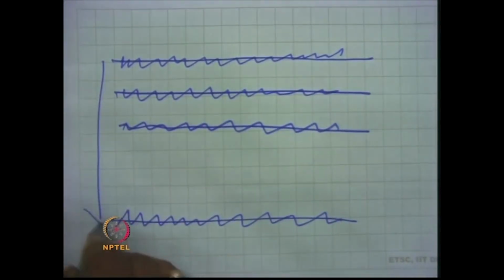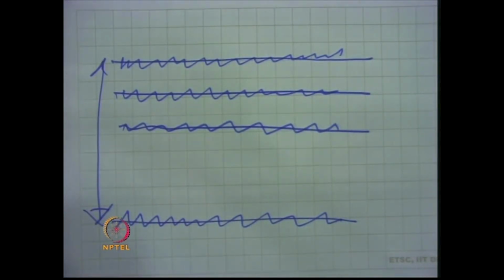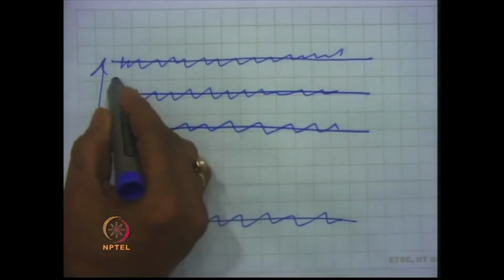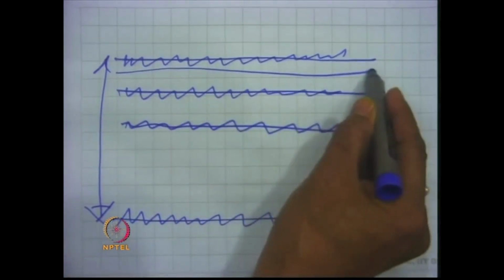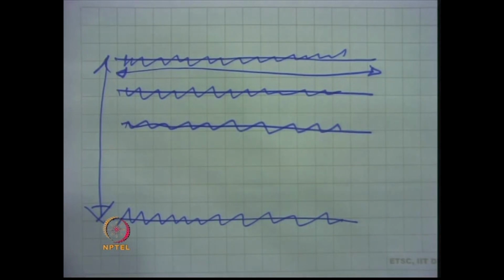The larger the number of time history records, the better the prediction. Ideally, one must have an infinite number of records in the ensemble. Similarly, the duration should be as large as possible for modeling the earthquake as a random process.